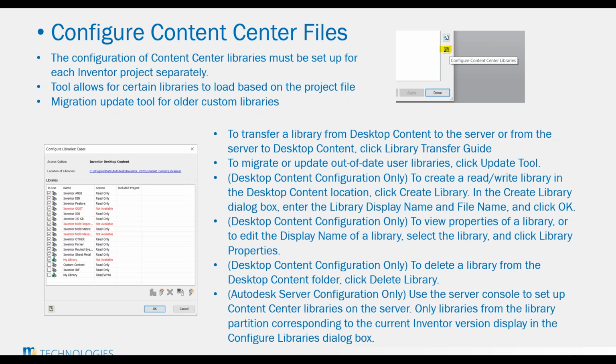This will dictate performance on your content center. When you first fire up the content center and you want to go ahead and drop in a bolt or a nut, you may wait a few seconds because it's taking time to load. So what you can do is you can come into your project file and edit it, or at the time of creation, you come into this dialog box and you uncheck the ones you don't want to load. And this will increase the performance dramatically.